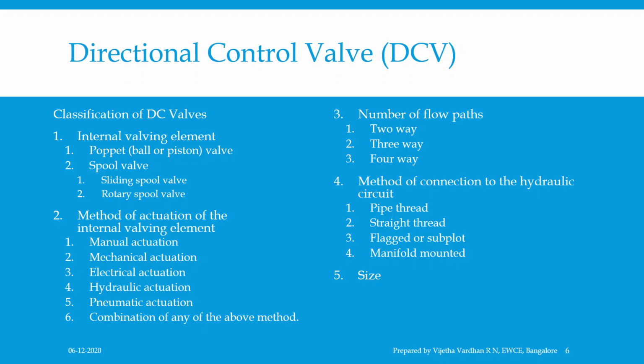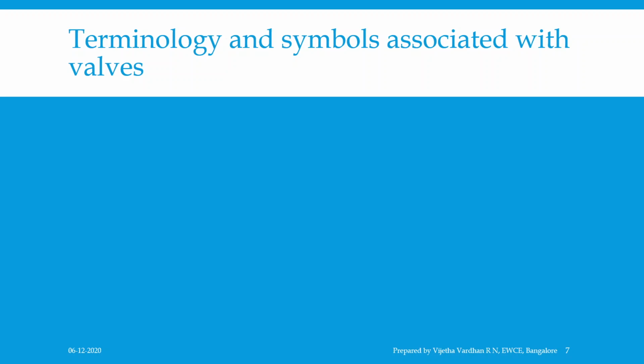And the direction control valves can be of either finite position or infinite position valve, but the majority of direction control valves used are of finite position type only. And these valves direct the fluid by opening or closing the flow paths in a definite valve position. As mentioned just now, each finite position is represented graphically by a square block and the arrow inside the square block showing the flow path.